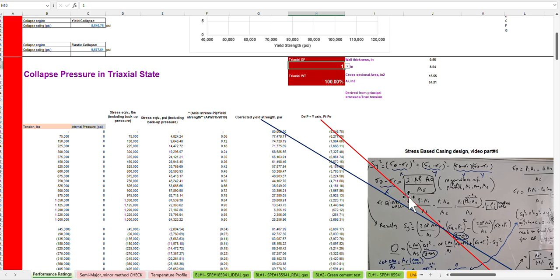The square root of values below 0 is not defined. That's why some tension values aren't giving a solution with a 1.25 design factor, because your yield strength is derated by the design factor, so there's no strength at those high values when you increase the triaxial design factor.